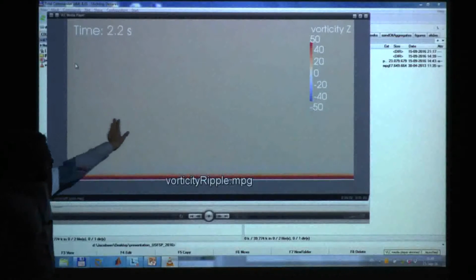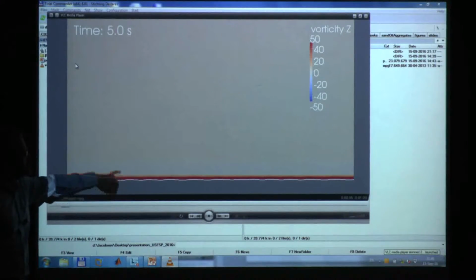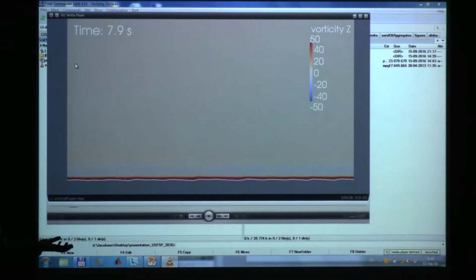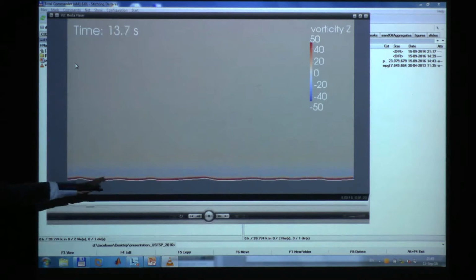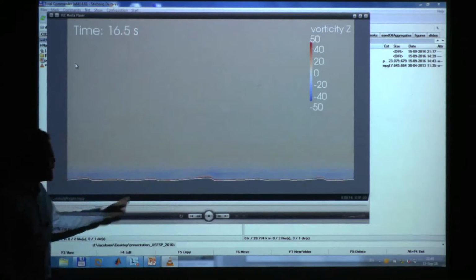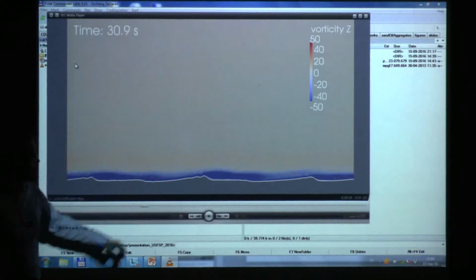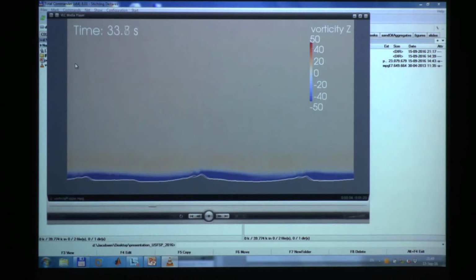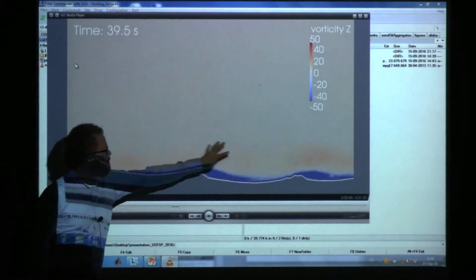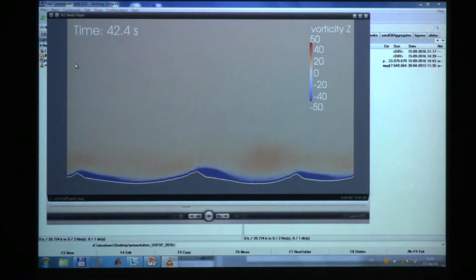What we have here is oscillatory flow. You can see the coloring is vorticity, so blue when the flow is in one direction and red when it's in the other direction. The bed becomes unstable. Small bed forms start forming, running back and forth, and you can see how the model actually allows these bed forms to merge. They become bigger, they become steeper. Elements of sand sliding on the steeper part will be activated here, and at some point they'll become so steep that you can see vortex shedding, which is these elements shooting off the crest of the ripples.